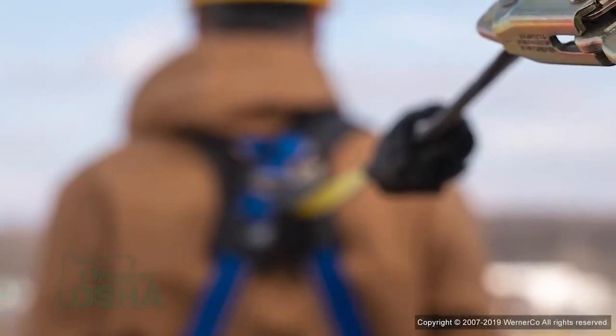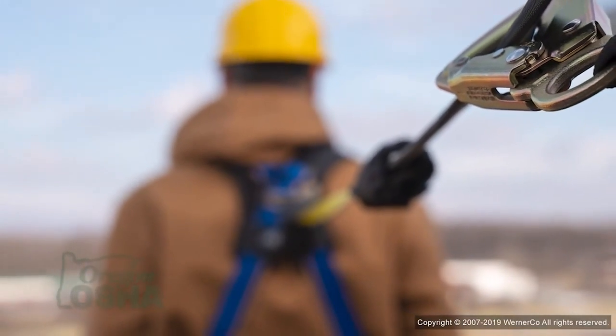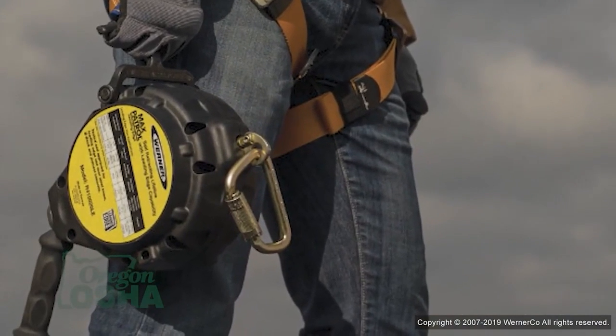I've seen a lot of them using fall restraint, simply because if you're working off of a floor, the idea is that you don't want to get to the point where you fall out, right? Another one that I've seen them using is the self-retracting lifelines. It provides a lot of freedom of movement. There's less worry about adjusting for the employee. Wherever they're at, it's adjusted correctly. And I think that's one thing that's really come into play that's helped some contractors buy into the fall protection.